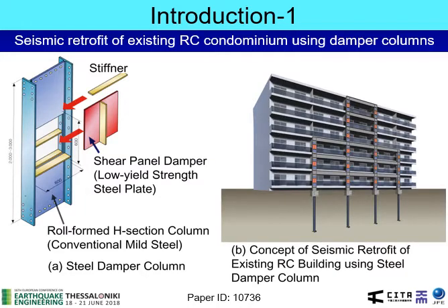The concept of seismic retrofit of existing RC building using steel damper column is shown here. This is the existing concrete condominium. A new steel frame is added on the balcony side of the condominium. This is a shear panel damper.